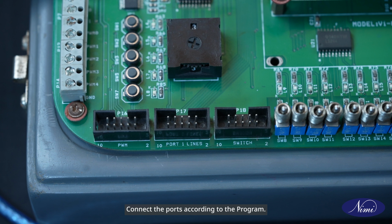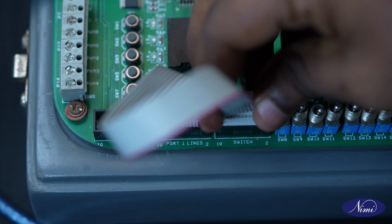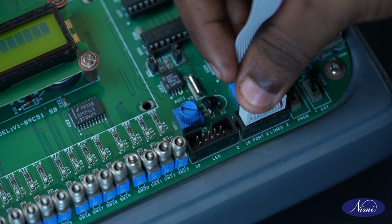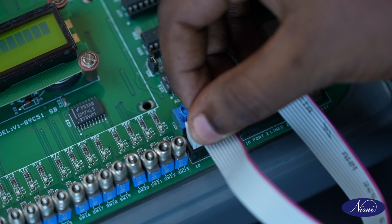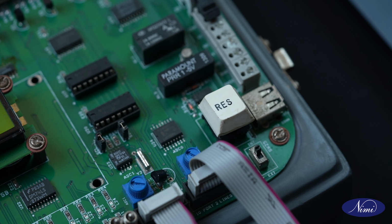Connect the ports according to the program. Locate the ports, switch, and LED in the kit. Use FRC cables female to female for connecting the ports. Here, port 1 is connected to the switch and port 2 is connected to the LED. Now click on the Reset button again to burn the program.